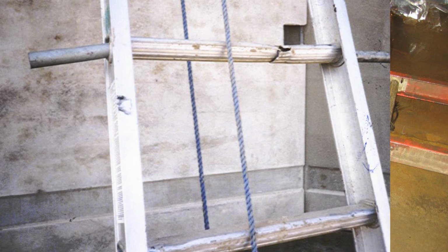How about the use of this ladder? This is being used on a job site. Notice the rung was broken, so what did they do? They stuck a pipe through there. Would it work? Yeah, probably. But did it meet manufacturer's recommendations? Nope. Should it have been taken out of service? Yep. Would you get a citation for this? Oh, yes. You know, with OSHA citations right now for a serious reaching over $16,000, hey, it's cheaper to get you a new ladder, right?